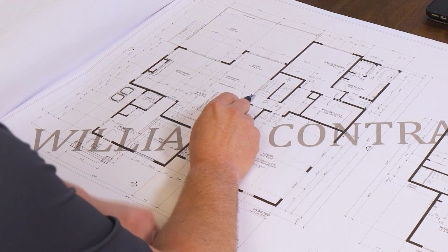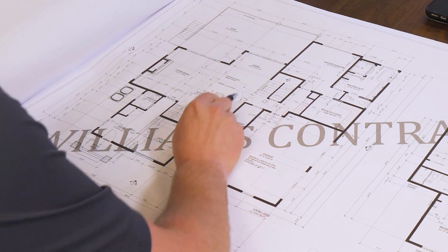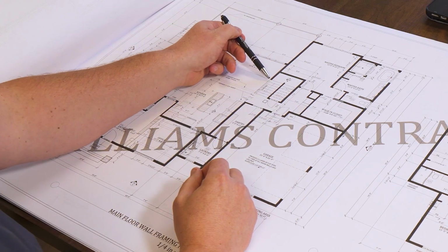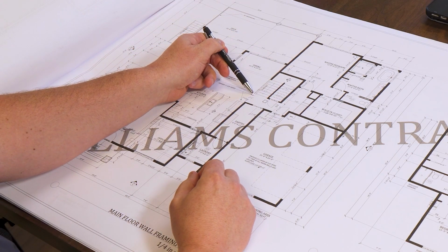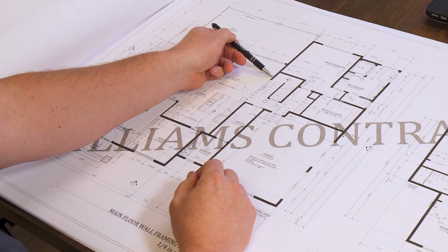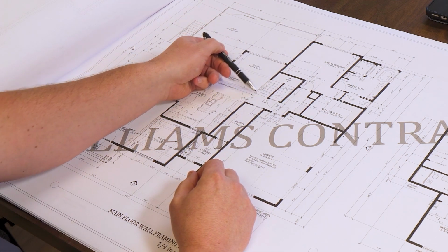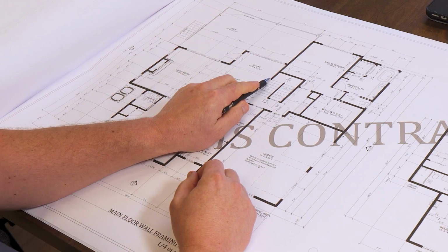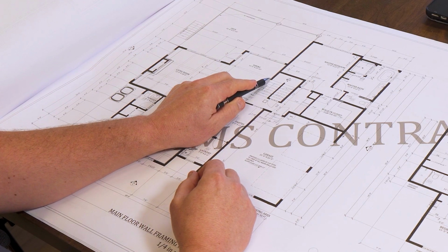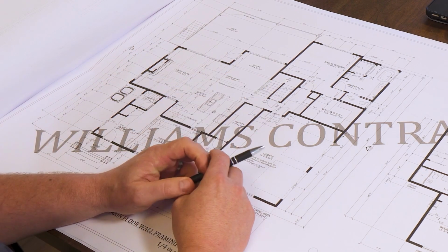And we'll highlight the stairs here. The handrail, we're showing that there's an open railing. So you've got the dark wall ends here. Open railing comes down. So the framer knows he's going to leave that space without a full wall. The full wall will end at this location and come all the way down. This communication for the stairs indicates the full wall ends with the edge of the landing.